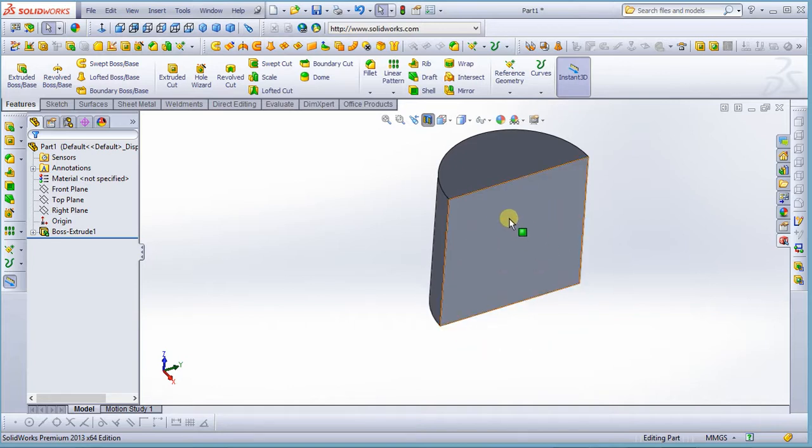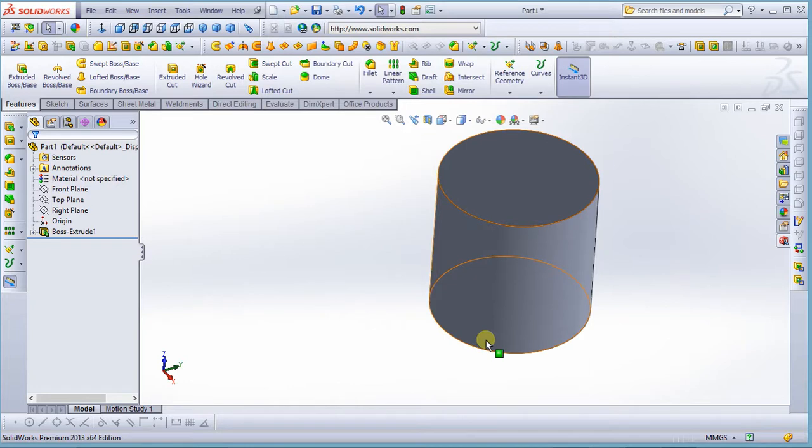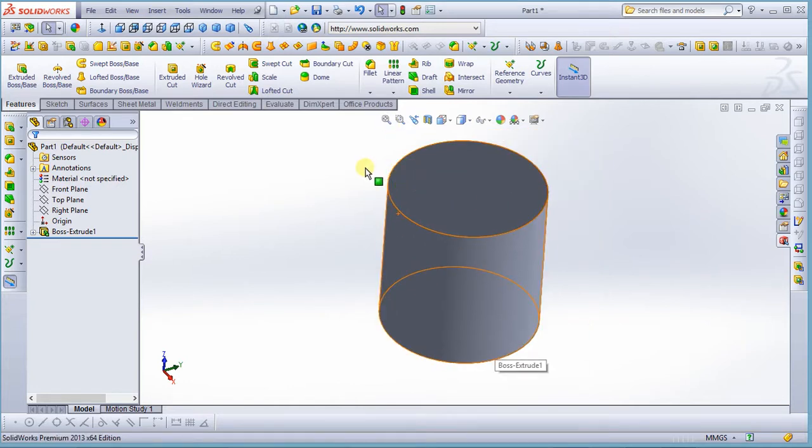When you want to sketch or make some drawing inside the internal part, you can do it easily with the help of a tool called section view. If you want to remove it and show the whole solid, you come to it, click on it, and you return to your normal view. You want to zoom fit it for it to show, come to zoom fit.